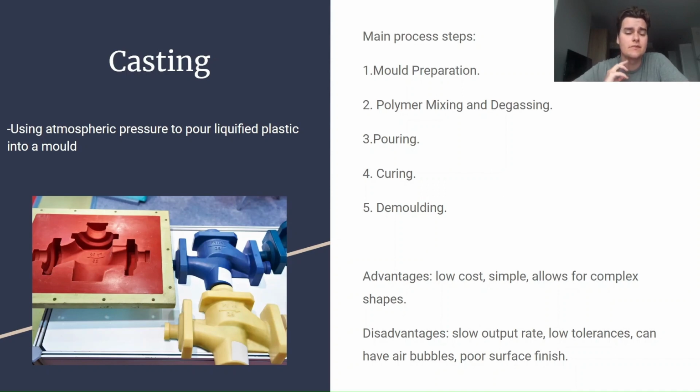The advantage of this method is a very low cost, simple method with great help to achieve complex shapes. The only problem is this is a very slow process, as it takes time to cure. The tolerancing itself is not the best due to surface imperfections and the potential for air bubbles. So these need to be taken in mind when using such a method.